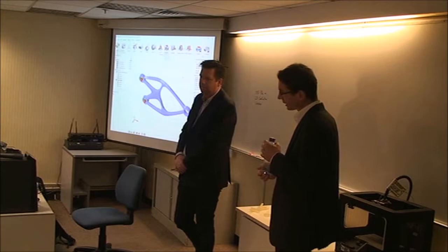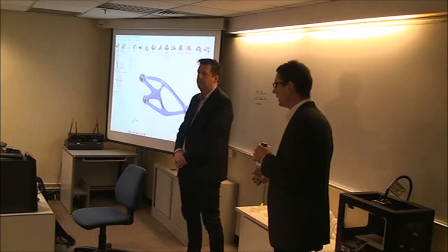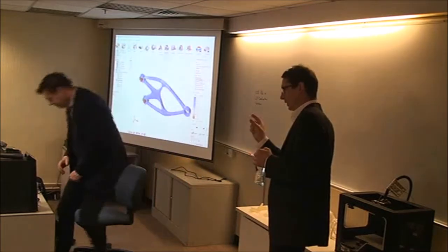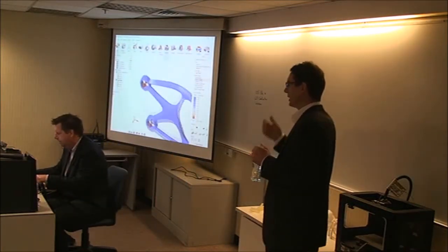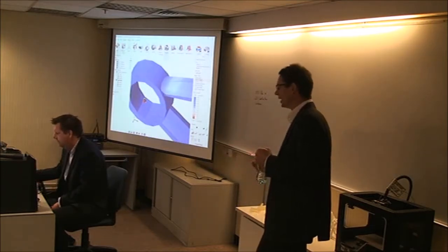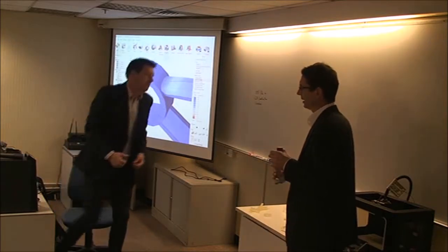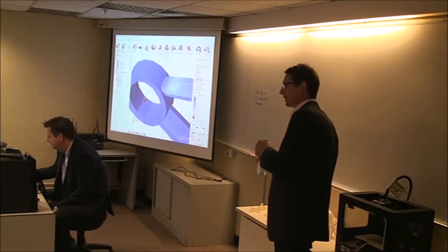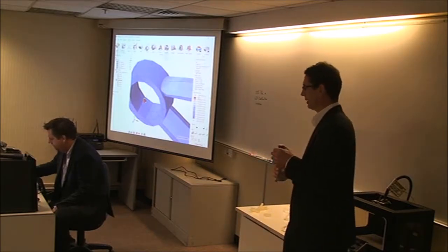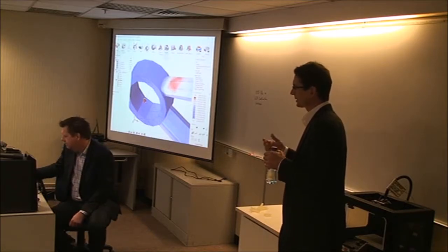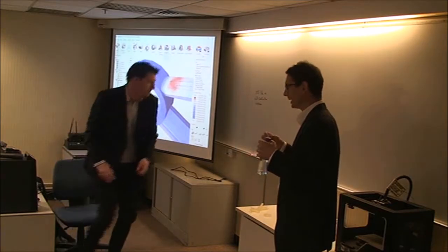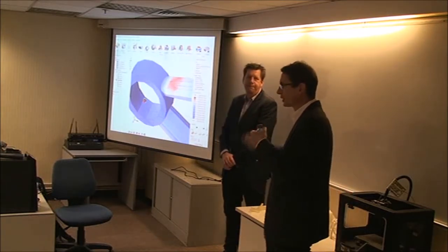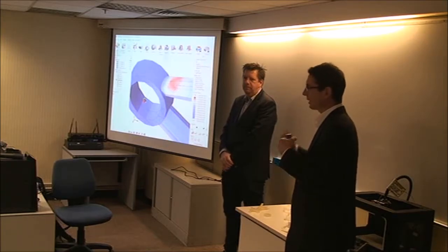It's not an analytical calculation, it is a finite element calculation. And finite elements have different characteristics. The element size can be larger or smaller, as can the type of element and the type of mathematical approach behind the element. There are different possibilities, and a scientist can work a lot and get slightly different results based on different mathematical approaches in the background. When you use the HyperWorks suite, we get access to a lot of these possibilities to change these approaches in the background, so you can do some research on that.